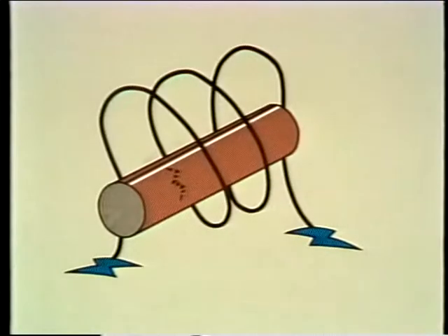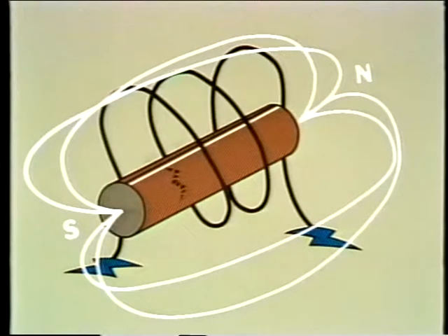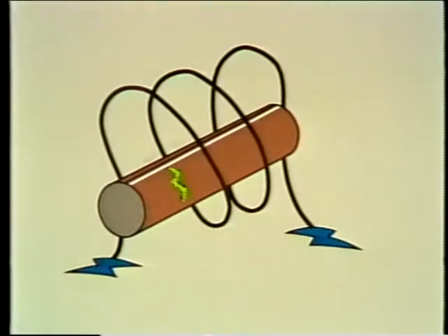Today, we'll be discussing 4 non-destructive testing methods that are often used in the plant. These 4 are magnetic particle, ultrasonic, radiographic, and liquid penetrant. The magnetic particle test, mag particle for short, can only be used on metals like iron or steel that can be magnetized. In the mag particle test, the entire part is magnetized and then sprinkled with a very fine iron filings. A defect is indicated where the iron particles clump together.